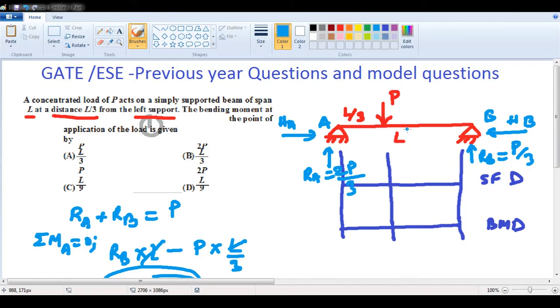Now we are focused over here to understand the bending moment. So the bending moment about this point, say this point is O. From here this is RB, which is at a perpendicular distance. So the bending moment will be RB into the perpendicular distance.